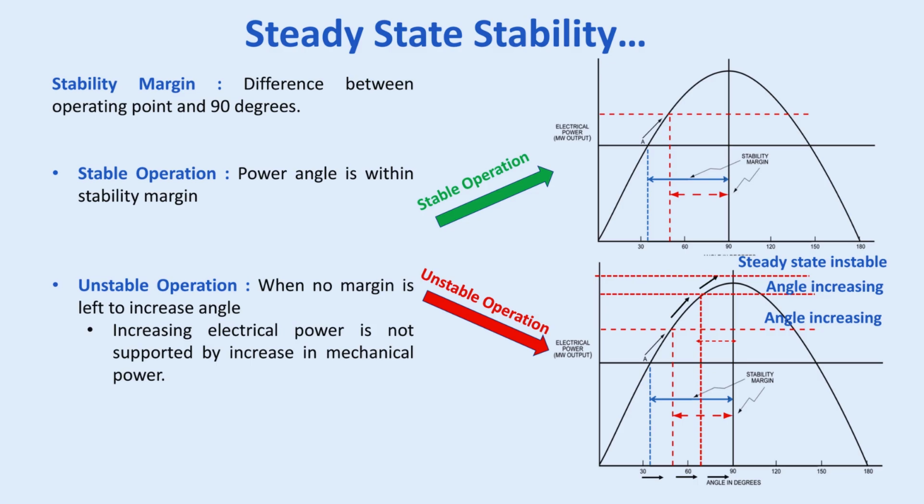Planners use these criteria in offline studies to figure out the maximum power you can safely schedule across transmission paths, ensuring you still have enough steady-state stability margin even after one of these events occurs. So meeting N-1 means making sure that even with a line out, the remaining paths aren't pushed to that unstable red zone for the power they need to carry. Exactly. You need enough margin built in.